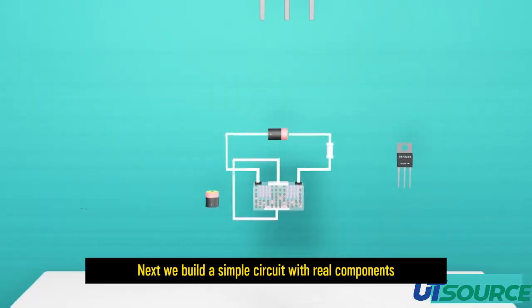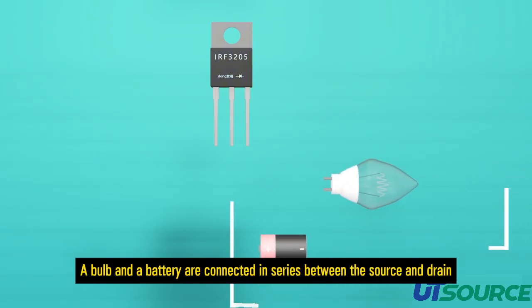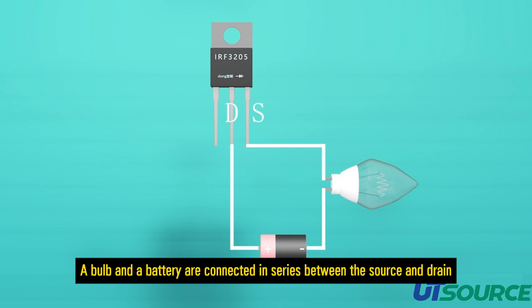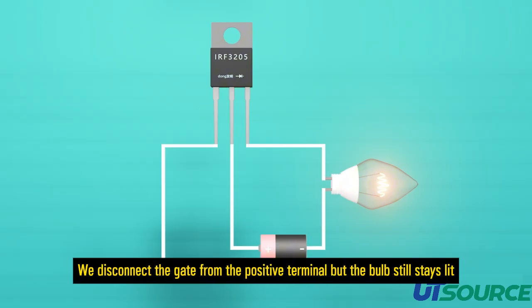Next, we build a simple circuit with real components. A bulb and a battery are connected in series between the source and drain. We connect the gate to the battery's positive terminal and the bulb lights up. We disconnect the gate from the positive terminal, but the bulb still stays lit.